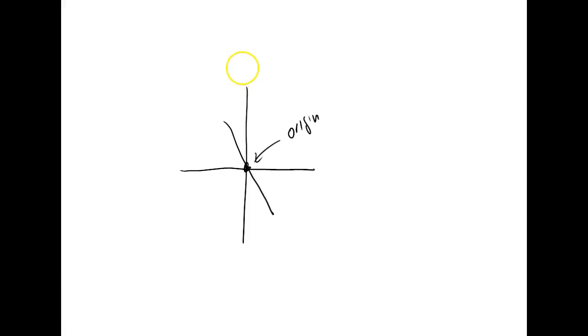So up this way would be what we call plus Z. And if I want the robot to go down, I can jog it minus Z. If I want it to go right, then I'll jog plus Y. And if I want it to go to the left, I'll jog it minus Y. If I want it to come out, I'll jog it plus X. If I want it to go back, I'll jog minus X. So now when we jog the robot like this, we're not concerned about what axis to move. All I'm concerned about is a direction. Y'all understand that? I'm concerned with the direction.